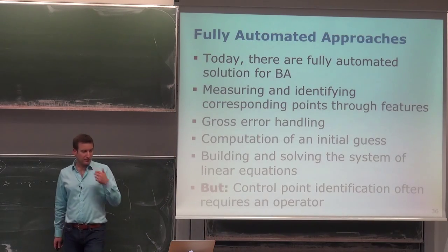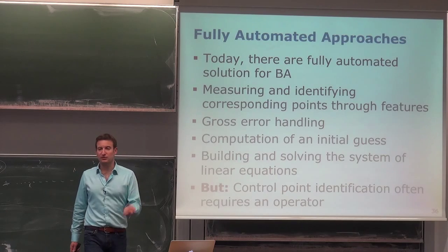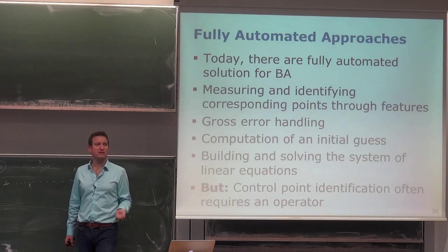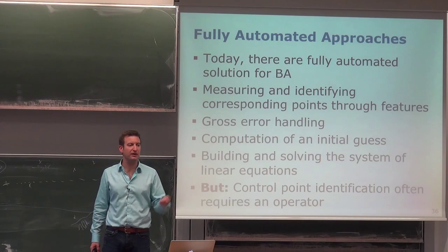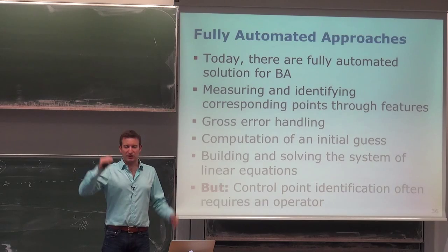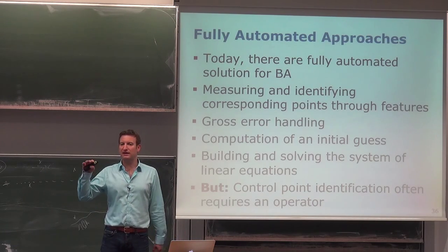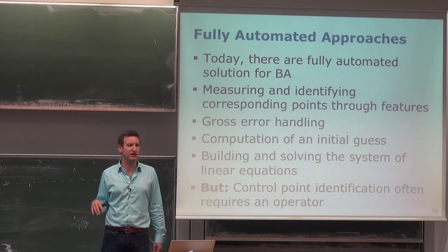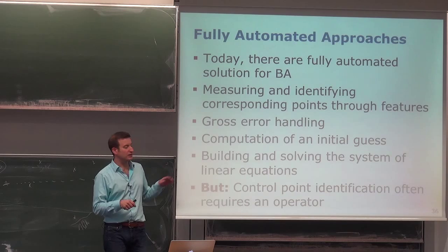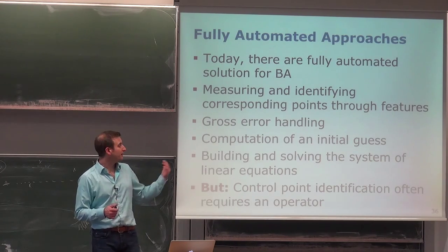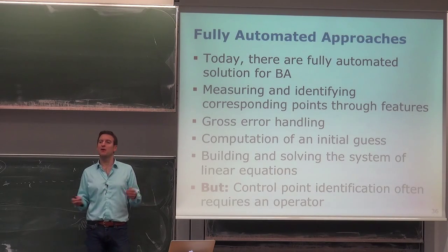So bundle adjustment is one of the approaches which has been around for quite a while and is one of the absolute standard techniques used in photogrammetry. It's one of the things where you can find existing solutions. There's commercial software out there which you can use, for example, if you buy a small helicopter or drone, put a standard GoPro on that camera, fly over a scene, and put this information into standard software you can buy in order to solve the bundle adjustment problem and come up with a map of the environment.